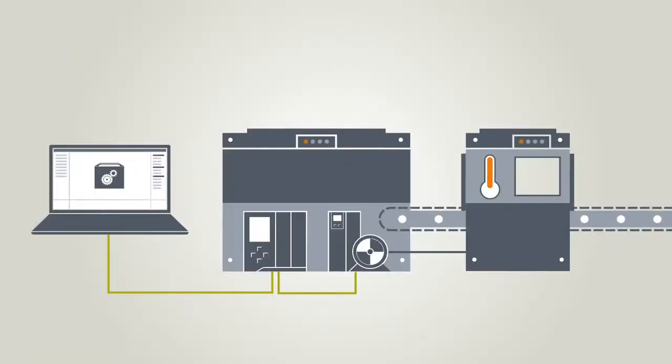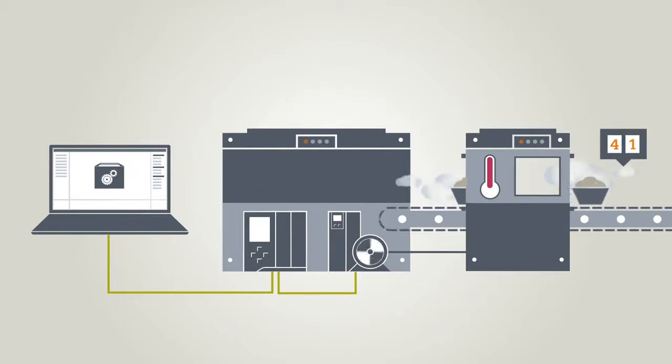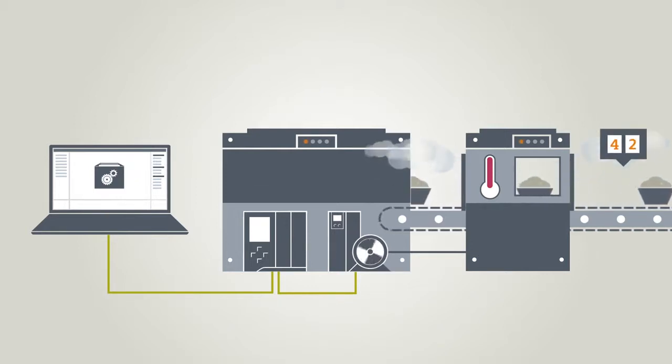For instance, the motion control technology object can control and position an actuator. The PID control technology object regulates physical characteristics such as oven temperature, keeping these at a specified value. The counting and measuring technology object manages the hardware for rapid counter inputs, for example for incremental encoders.